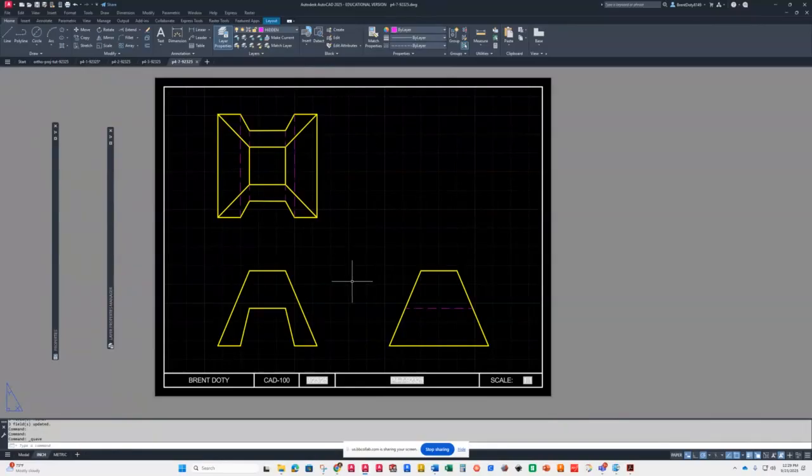So what happens if your lines, when you activate your viewport, don't show up correctly? Well, what you do is you type in LTS, enter. And typically, inch drawings will be set to 0.5 or 0.75, anything that's less than 1. Metric drawings will be over 1, and they're usually above 6. It depends on the scale.